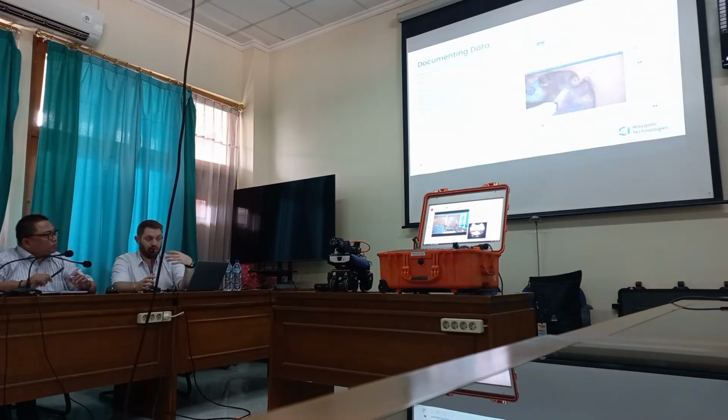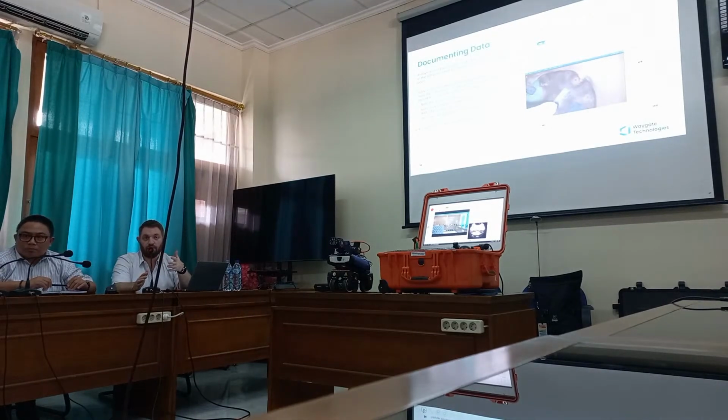Documenting our data is really critical. If we've mislabeled images or NDT data, it can give the client a false representation of what's there. A nozzle that might be called K1A that we've labeled N6 that might have corrosion, the client might actually go out and remove that nozzle, cut it out, and replace the wrong nozzle. I've seen this happen many times in the industry, once in New Zealand where they cut the wrong nozzle out thinking it had hydrogen attack, and it was actually a different nozzle.